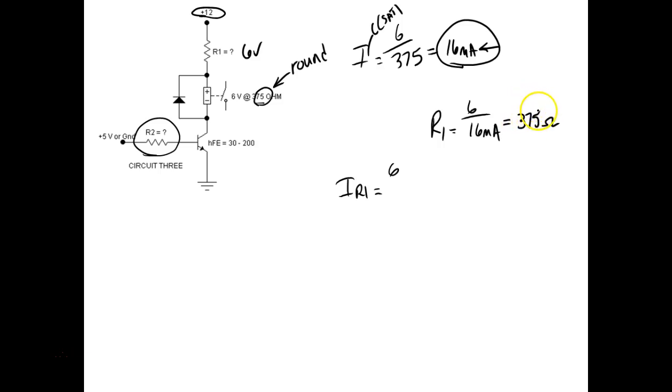Yeah, so we'd look at this guy. Well, we'd look at that guy first, which means this guy would go to an 8, right? Y'all understand? And then this guy would go to a 4, but we don't have to do that because what's the next? So here we would round up. So it's going to be, do we have a 3.8K? And you don't even have to worry about the tolerance on this guy, right? You understand? Because it's not critical like this guy is right here.